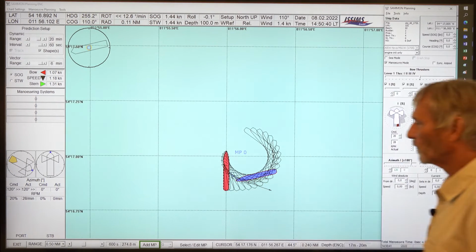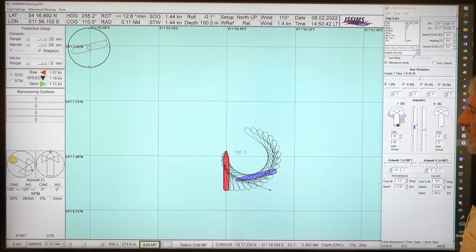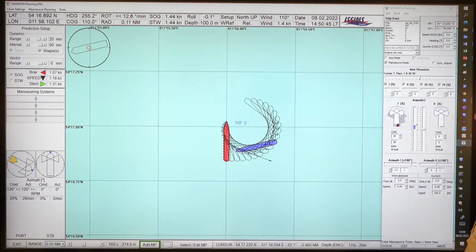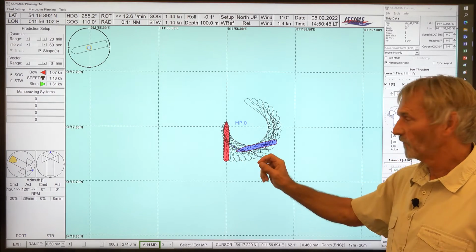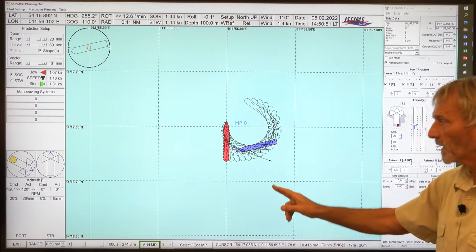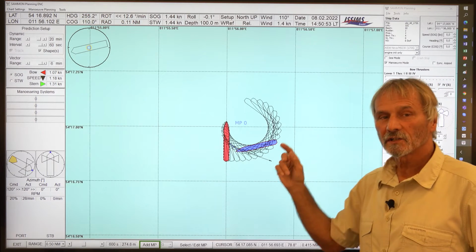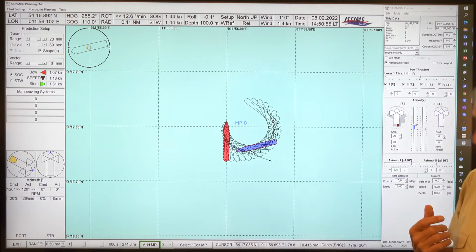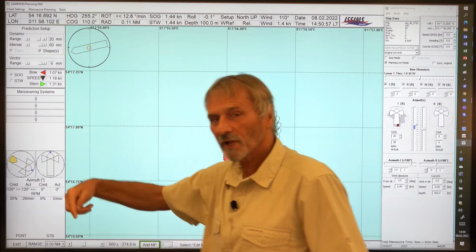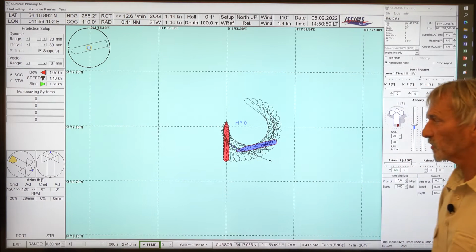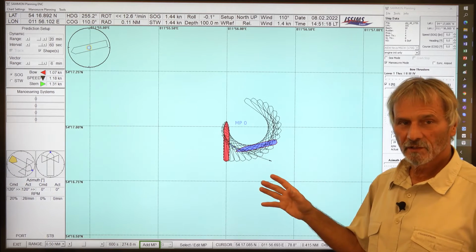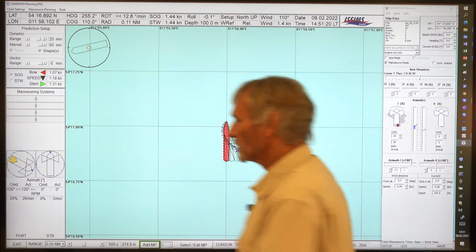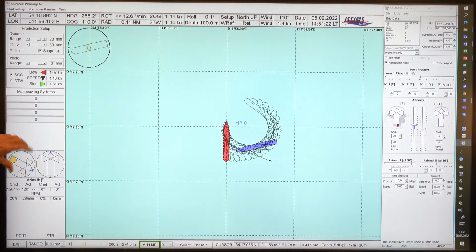I'm using it now for 120 degrees. We see that for a resulting pod force to 120 degrees, the ship starts pulling astern already, because the pod is already creating a force astern. In this case, we always use the port pod. So it's in the inward configuration, inward.